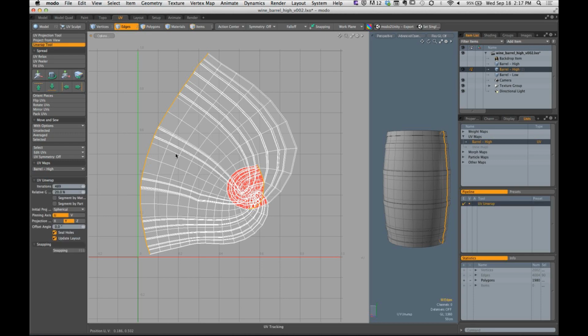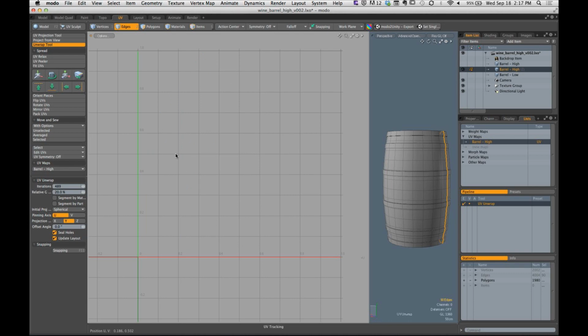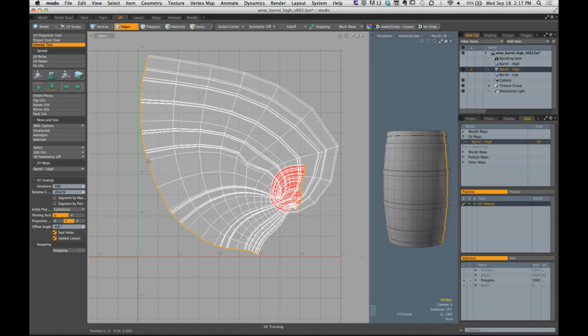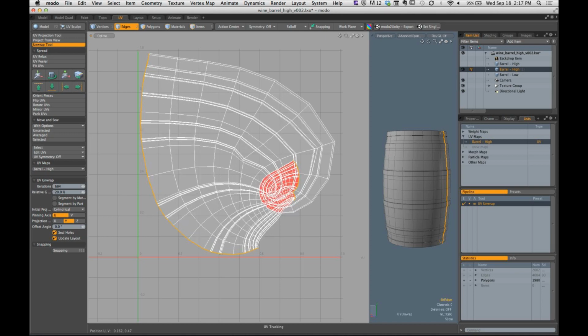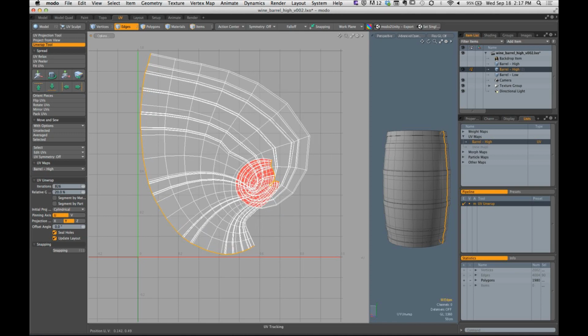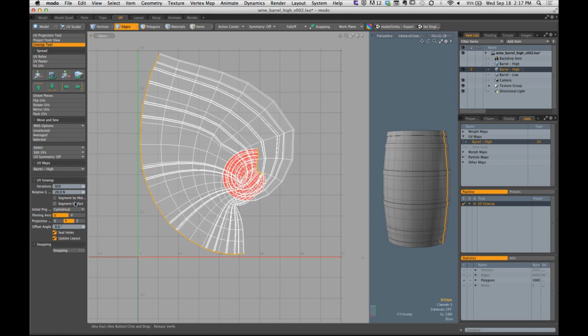Or, okay, it's going to make a liar out of me twice in this particular situation, all right? So let's change the initial projection type to cylinder. Left click and drag. And it's still not giving me a really fantastic result. Let me just keep going here. I'm just left clicking and dragging. Really what we're doing when we're left clicking and dragging with the UV Unwrap tool is that we're interactively changing that iterations value.